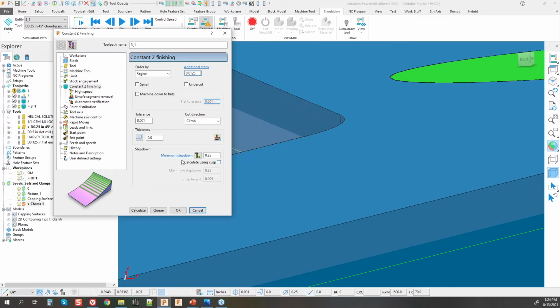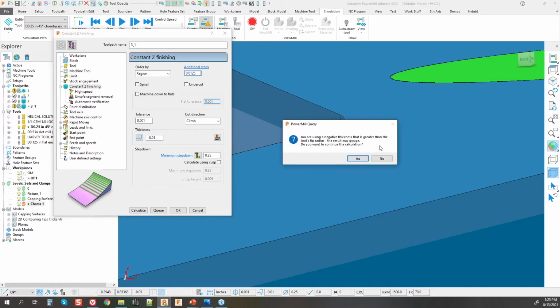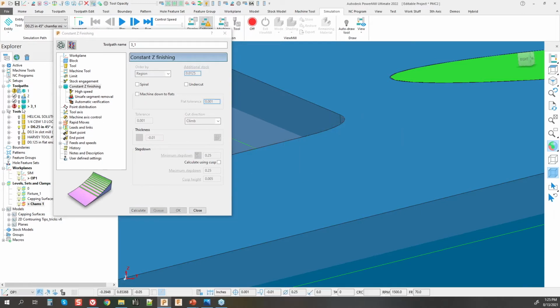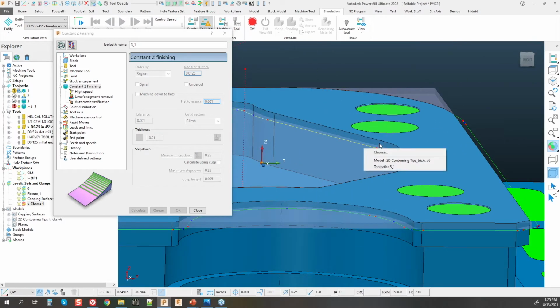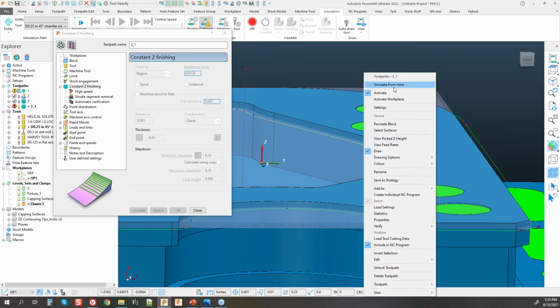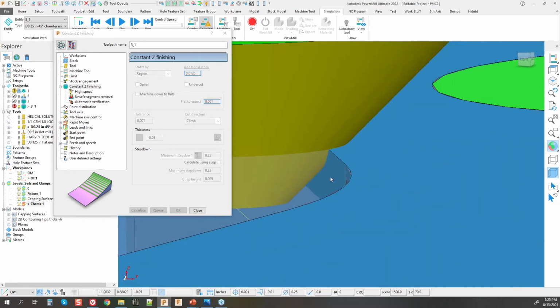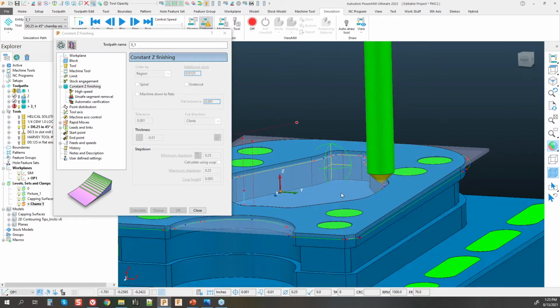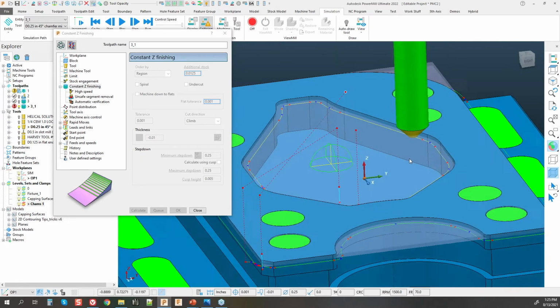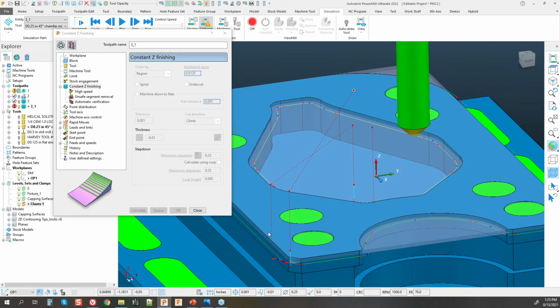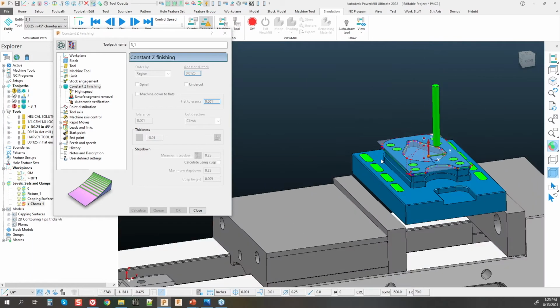Well, a lot of users just simply come in, and this is more of a trick than anything, and just define a negative area on your thickness for both axial and radial. Once you calculate that, you will get a red toolpath if you have automatic collision set. However, as it is gouging the part, you'll also be chamfering that by that 10 thousandths, giving yourself a nice 45 degrees on there. So rather funny. It's a nice fast way to come in and start chamfering around features on your part.